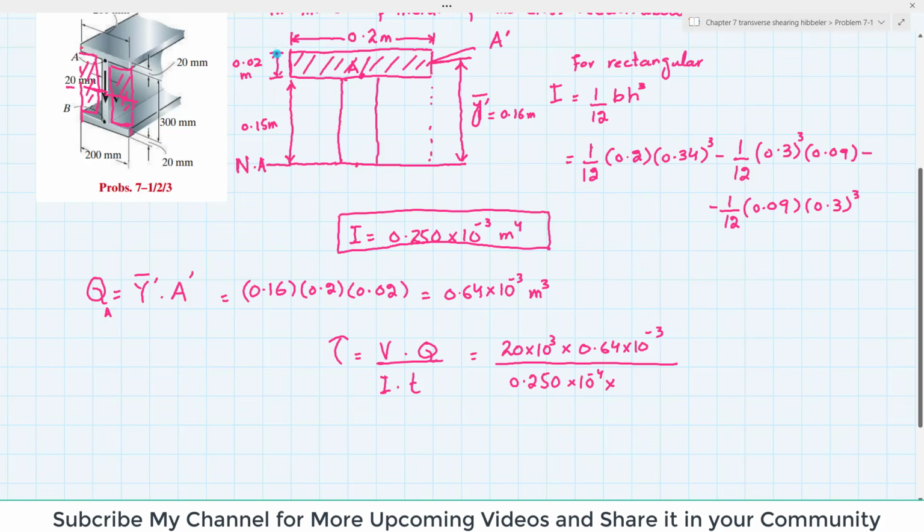Sorry, this t is the thickness, clear? So 0.02. When you calculate it, you will get the shearing stress equal to 2.559 into 10 to the power 6 Pascal, or the shearing stress at point A is equal to 2.56 megapascal. So this is the shearing stress at point A.